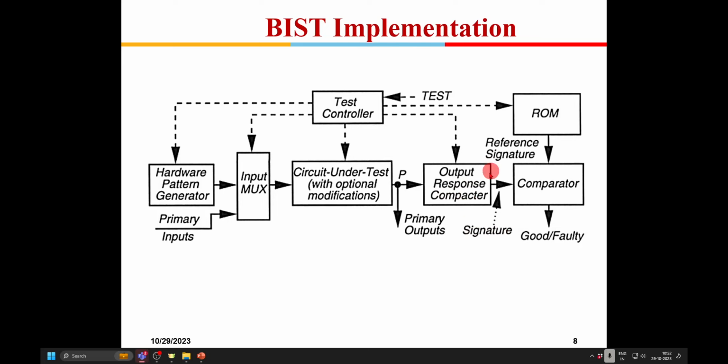It is known as a signature, and this is known as a compactor. That means the entire results will be compacted, and you have a single result coming out of 1,000, and then it will generate one 64-bit data signature or something like that, which we'll compare. And if it is not matching, then we might rerun a detailed analysis of each input. But in the first go, we will use a signature, so that will save the total time, because you don't expect things to fail very often, right? Failure is an exception rather than a usual occurrence. So that is the reason we use a compactor.